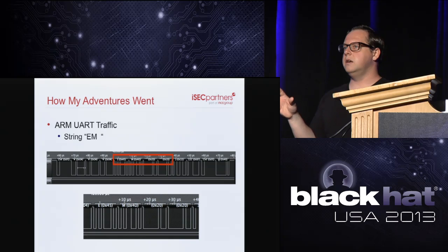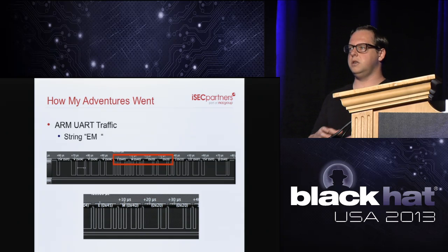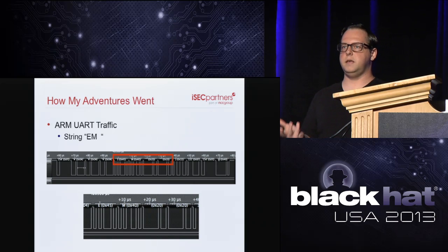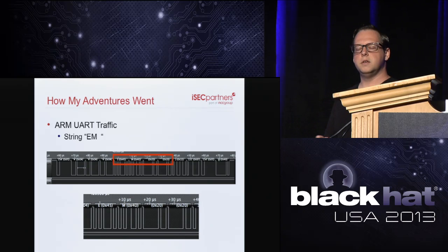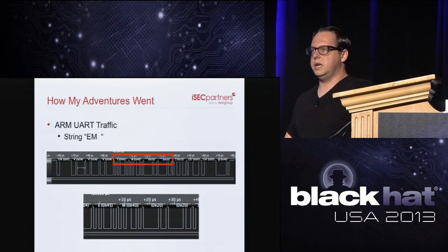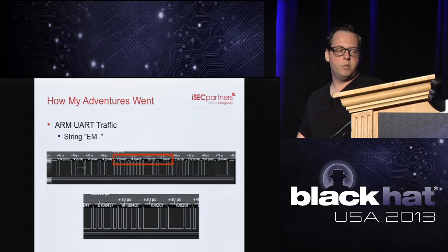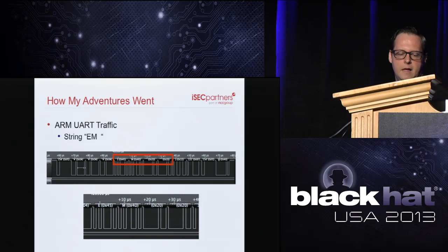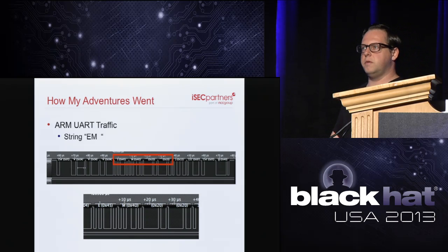So in any Thunderbolt implementation, you need the Thunderbolt controller, and you also need an ARM Cortex. The ARM Cortex and the Thunderbolt controller have to be together. This is kind of an interesting correlation, that they need to be together. So let's grab some Thunderbolt firmware updates, and maybe we can find some of these strings and some other things in these firmware updates. We notice the string EM space. Maybe we can find that in the Thunderbolt firmware image and see how the Thunderbolt controller talks to the ARM and sets it up. Let's try and figure that out.